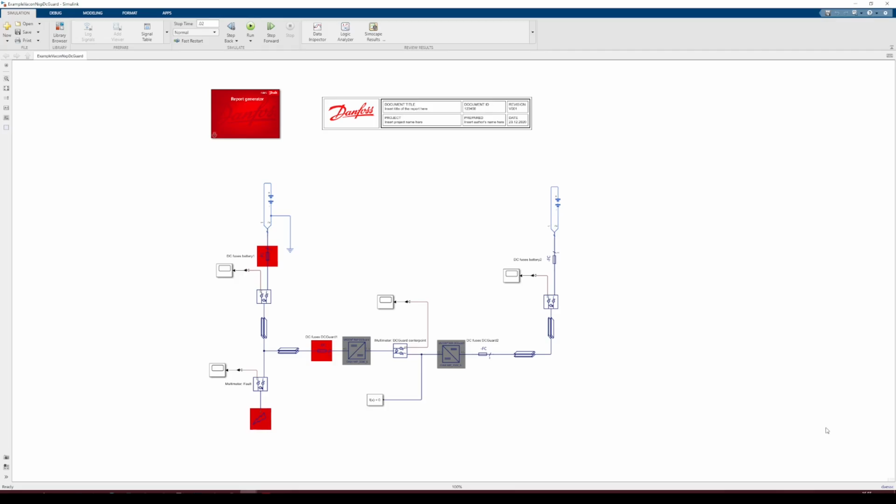In this simplified schematic, we have a DC distribution circuit with the DC card here in the middle, and on the left-hand side, we have a battery system. At this node, we are generating the fault, and on the right-hand side, we have a second battery here. So both batteries have their own DC fuses. Also, the DC cards here have their DC input fuses, and we have defined the conductor segments or the bus bars using these component models here.